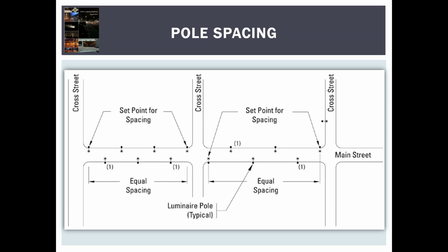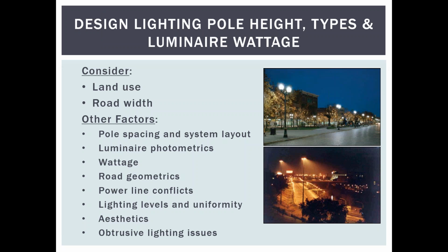And one thing I want to point out, based on past experience: if you're going to have mid-block trail crossings or mid-block crosswalks, make sure you do coordination with the lighting and the trail crossings, or locate the trail crossings to where the lighting is going to be. I've seen some bad examples where this just has not been done, and sometimes the trail crossings were put right in the middle of two separate light sources where the lighting is the least intense.